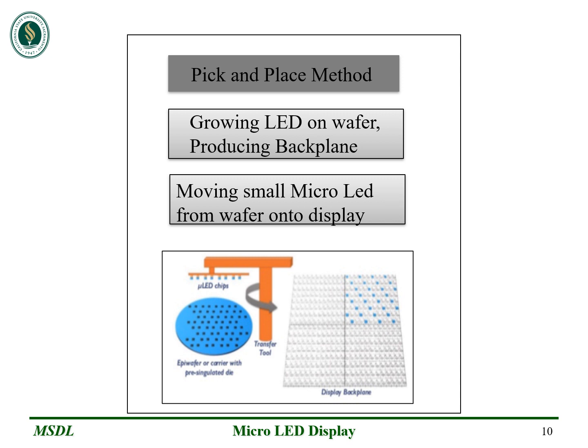Existing pick and place assembly equipment can only achieve plus or minus 34 micrometer accuracy, though it is multi-chip per transfer. Flip chip bonding typically features accuracy of plus or minus 1.5 micrometer but only for a single unit at a time, thus production speeds are slow.